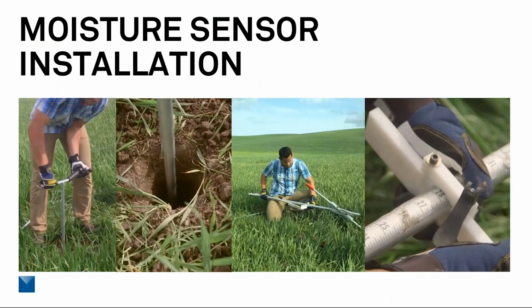Now, here are some pictures of what that looks like, because a lot of people have asked me, how do you actually do that? There's Leo with the auger. He's augering out the soil in our install hole. He's got the tool in his hands in that third picture over. He's setting the depth so that we can set the sensors in exactly the right spot in the soil. And you can see the markings on the install tool there. It comes in inches and in centimeters.